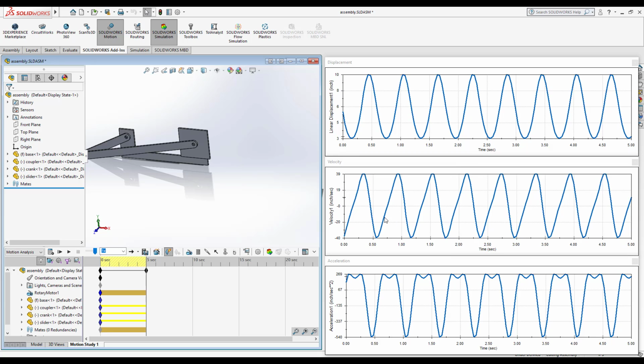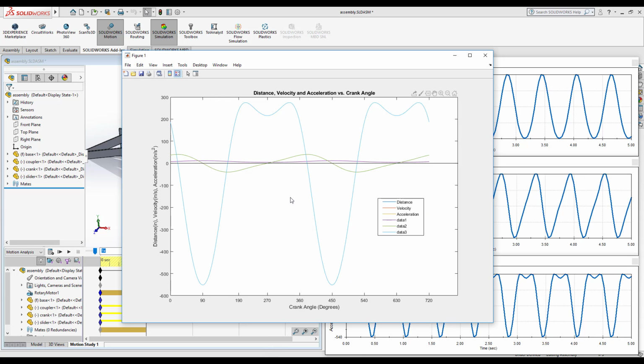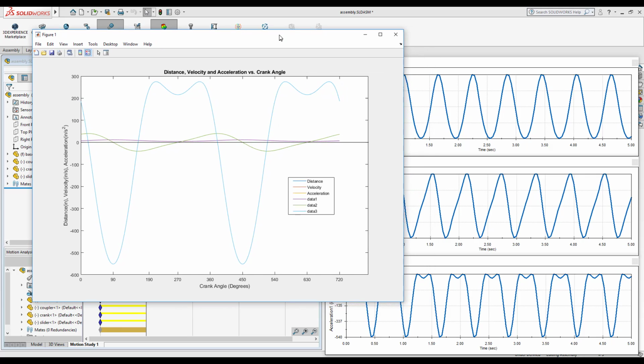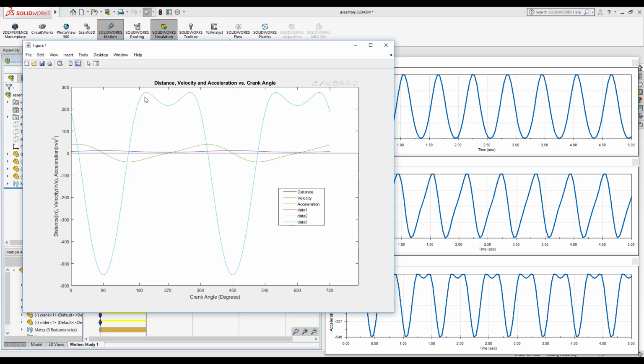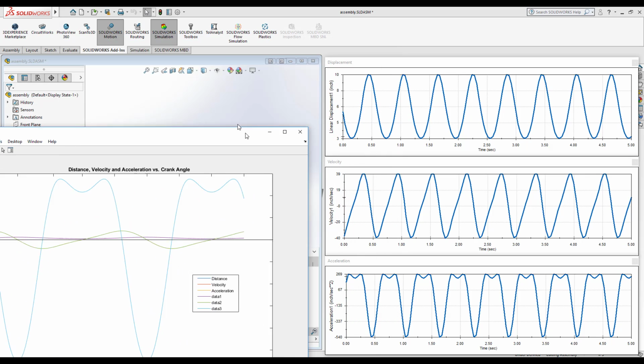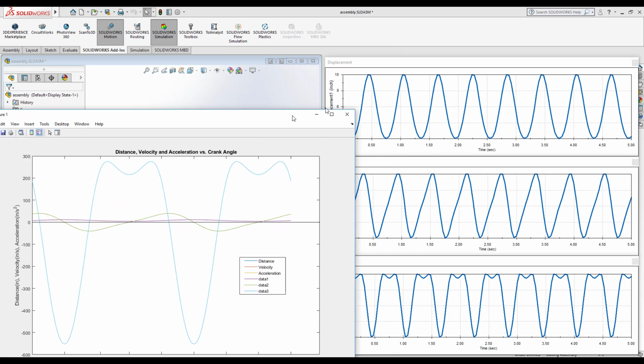And you can see that the slope of this has a slightly forward bias, which when you go back to MATLAB, it's true there as well. And then for the acceleration, it has the same double hump. And we're also getting the same values for the most part. You can see that the lowest acceleration is around negative 540, and when you check it on MATLAB, it's also negative 540. And the maximum acceleration is 269, which matches up with what MATLAB is providing. And the same goes for the velocity at the max being 39 and minimum being around negative 40.